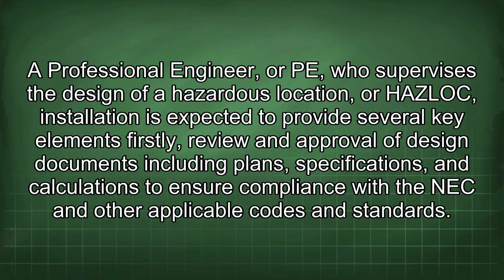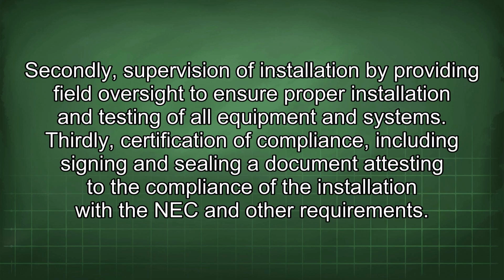Firstly, review and approval of design documents, including plans, specifications, and calculations to ensure compliance with the NEC and other applicable codes and standards. Secondly, supervision of installation by providing field oversight to ensure proper installation and testing of all equipment and systems. Thirdly, certification of compliance, including signing and sealing a document attesting to the compliance of the installation with the NEC and other requirements.